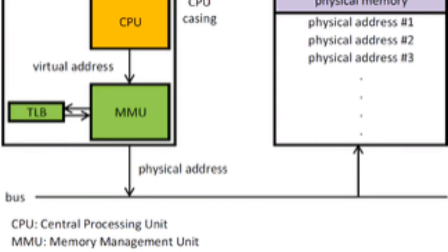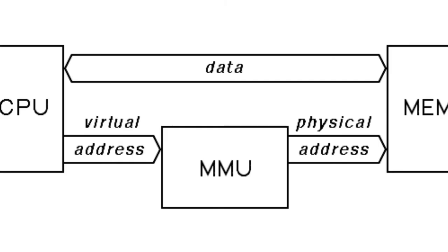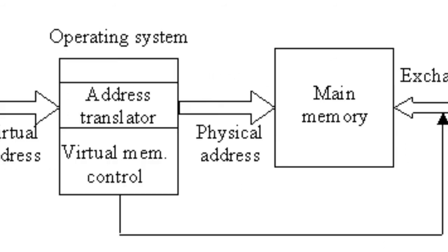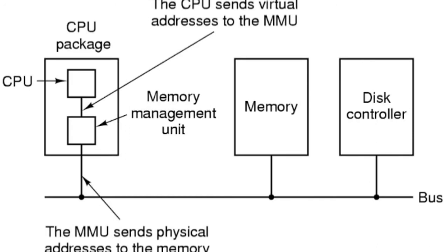And now let's talk about the MMU, which is the Memory Management Unit. Most high-end microprocessors in desktop, laptop, and server computers have a memory management unit translating logical addresses into physical RAM addresses. By the way, logical addresses are 0s and 1s, which is nothing but binary. This provides memory protection and paging abilities useful for virtual memory. Simpler processors, especially microcontrollers, usually don't include an MMU.